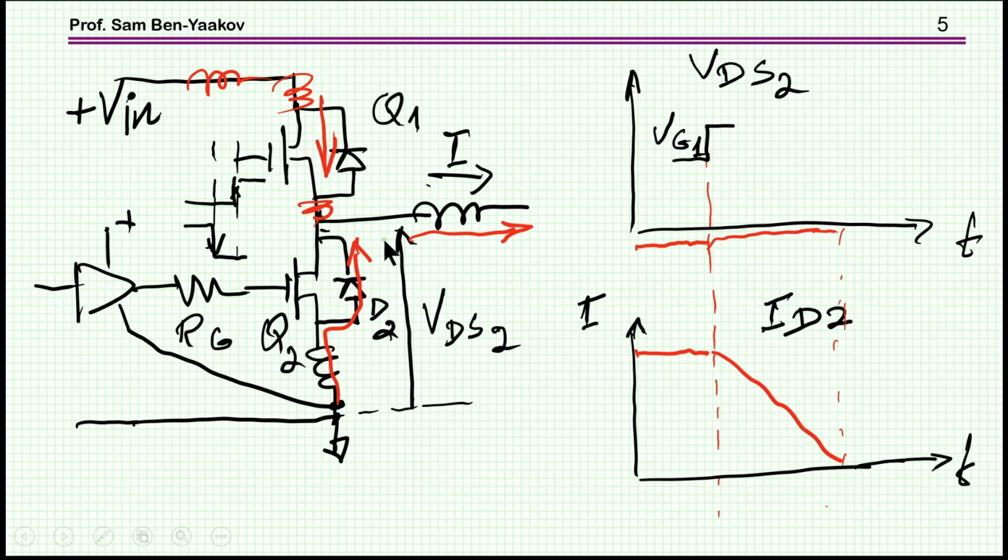Now, we are turning this transistor on. As we turn it on and it starts to conduct, we are imposing a positive voltage here. And consequently, the diode current will start going down. If it is a quick switch, then this would be like a resistance, R_DS(on), but due to the leakages in the line, the current is not building up quickly, but there is a certain slope depending on the voltage and the total stray inductance in the loop.